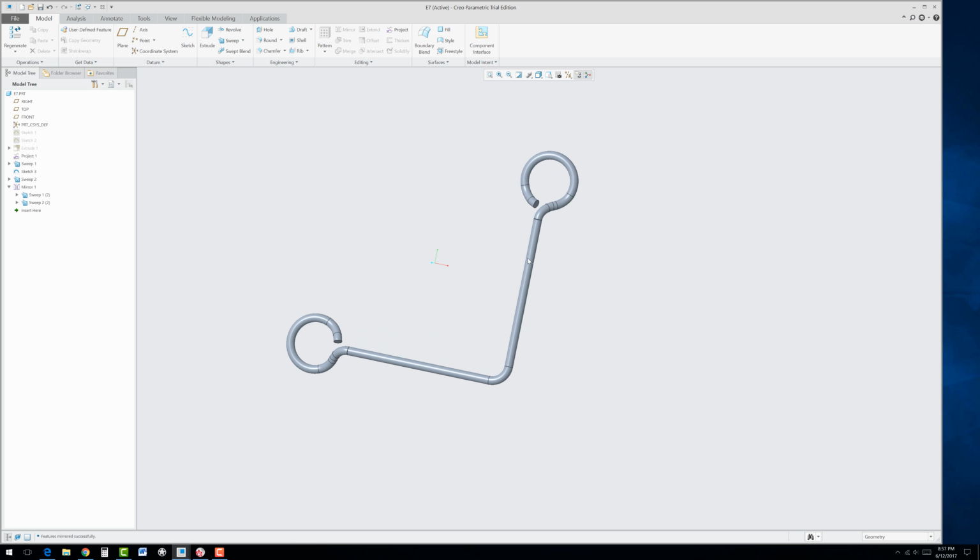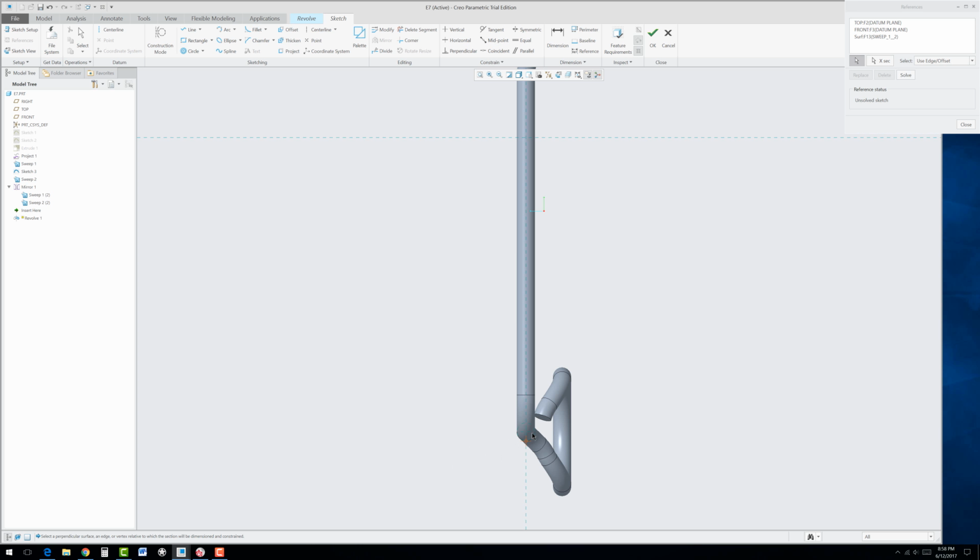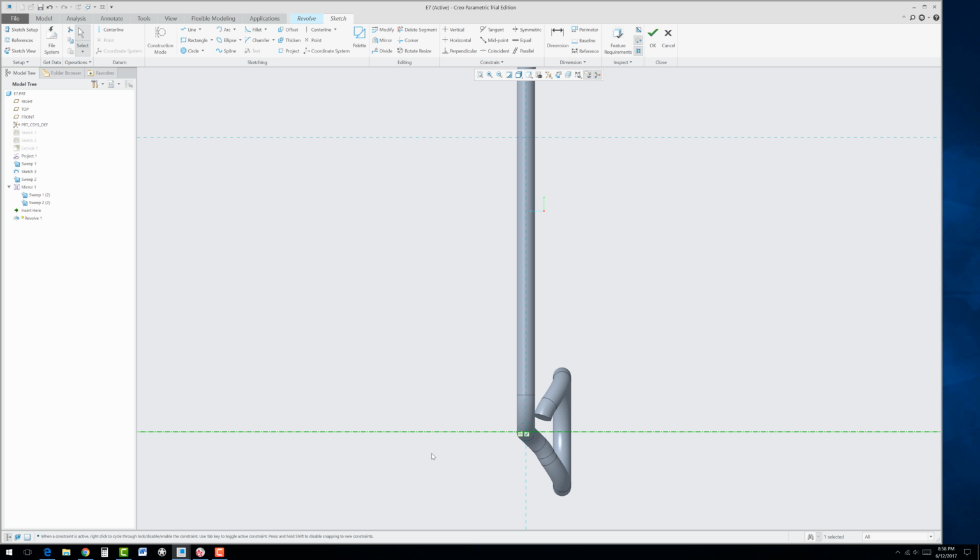Okay, down below, go to reference up here and make a reference right at that point. This is going to enable us now to draw a center line right at the center of that circle. Let me make sure I have it selected and draw it horizontal across. That is our theoretical sharp corner, the center point of the entire model once it's complete.